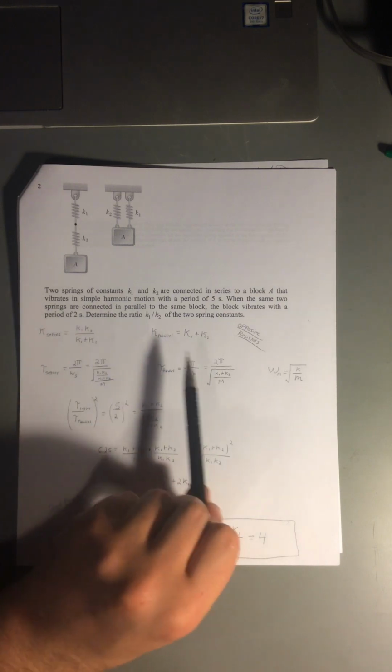And so from our lectures and the textbook, we know that adding springs to find an equivalent spring is actually the opposite of what you do when you want to find an equivalent resistor. For springs in series, we add the inverses, 1 over the spring constant. But since there's just 2, we can do K1 times K2 over the addition of the spring constants, K1 plus K2. And then in parallel, it's just a matter of adding the spring constants K1 plus K2 together.